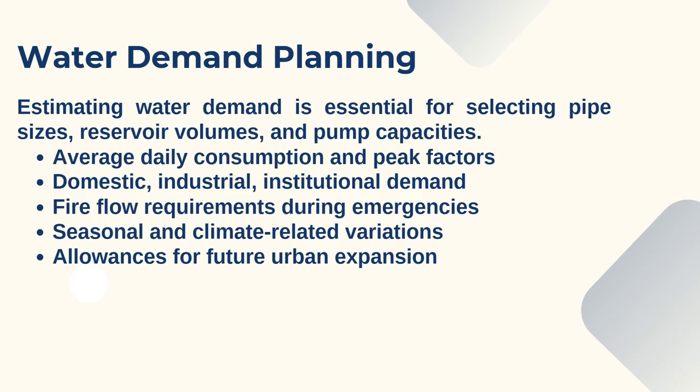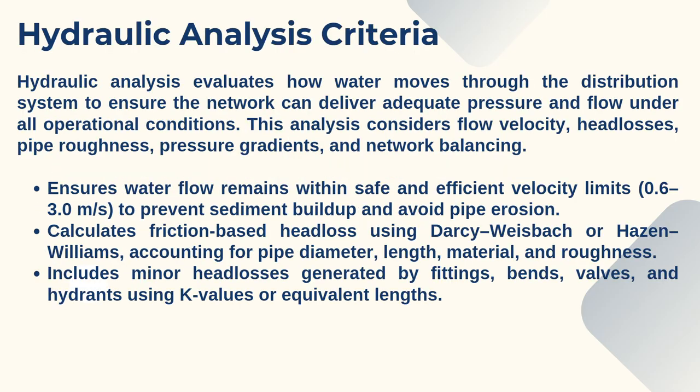Next is the water demand planning. Estimating water demand is essential for selecting pipe size, reservoir volume, and also pump capacities. This includes average daily consumption and peak factor, domestic, industrial and institutional demand, the fire flow requirement during emergency, seasonal and climate variation, and the last one is allowances for future urban expansion.